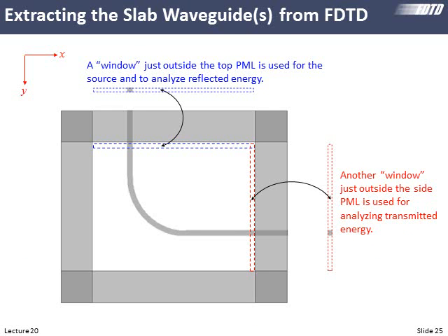So at first, we won't know anything about our waveguide finite difference analysis. We think we're doing a two-dimensional finite difference time domain simulation, and we will. So we build our grid, we build our PML, we build the waveguide on it, and here maybe we're studying a waveguide bend. We want to launch energy into our waveguide, we want to see it go around the bend and exit. And maybe we're studying how much of that is leaking out so we can figure out how tightly we could bend our waveguide without losing the energy. So what we'll do is we'll look at this little window in the cross-section of our grid. And this is what we'll analyze in our finite difference method. We'll look at that cross-section and calculate all of the modes that exist. And we'll use that to source the waveguide.